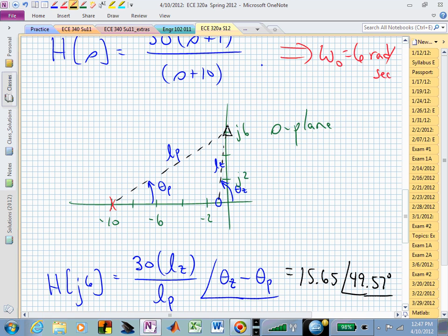We're doing the same exact thing for all of our poles and zeros. But we do have to keep the transfer function in pole-zero form, and we need to make sure we account for that gain. Likewise, the angles: we look at all the angles contributed by the zeros, those are upstairs, those sum, and then any pole angles, which are downstairs, those subtract, just like we do with complex numbers. Yes, question?